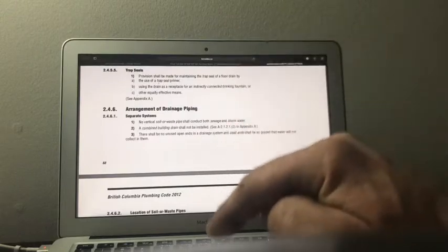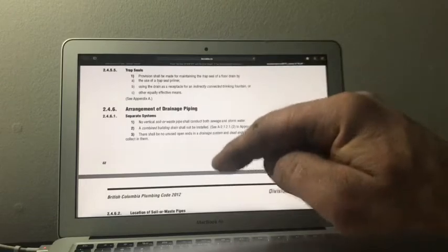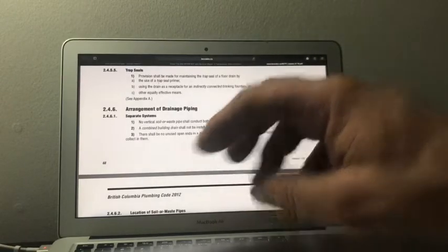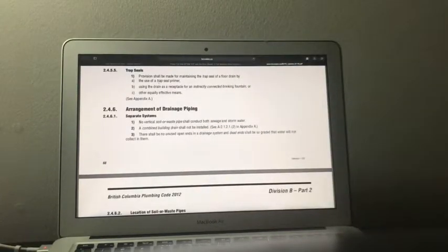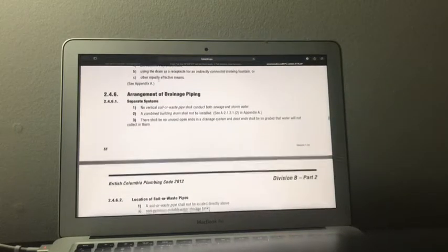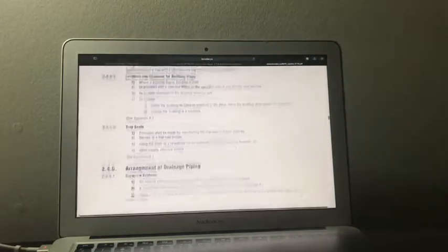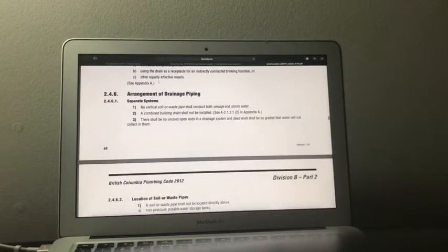To touch back on these floor drains, so for the young guys, just a little trap primer there, and that can feed just the floor drain itself, or a trap primer and then a distribution box, which serves up to 4 heads that would go in a wall. All those 4 lines would pop up in a wall, go to the distribution box. I've been in installations where they traditionally put access covers for those boxes, but 50-50, I've heard. So that's my experience on that.